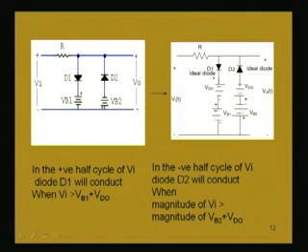Both these diodes actually have the same drop Vd naught, along with the ideal diode, with the conventional way of denoting the polarity of the Vd naught, that is the diode conduction is in this way. So, Vd naught will have positive polarity here and negative polarity here. So, this is the way of showing the equivalent model with the battery polarities like this.